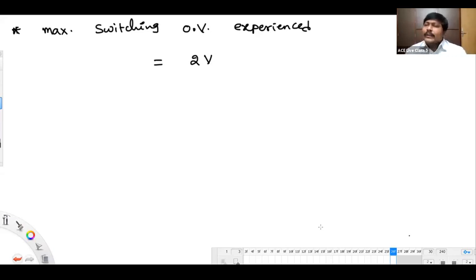That's why we are not interested in doing the AC transient analysis, because we are getting it now. We are getting that AC switching overvoltage also by an extension of DC, so you need not do the AC transient analysis separately to know what that overvoltage is in this basic analysis.